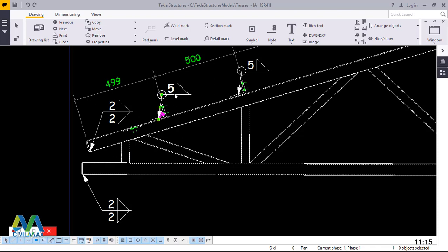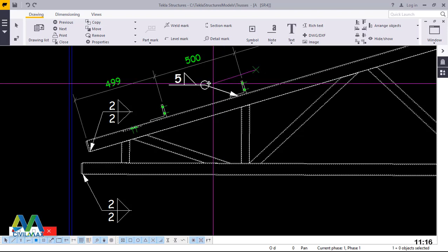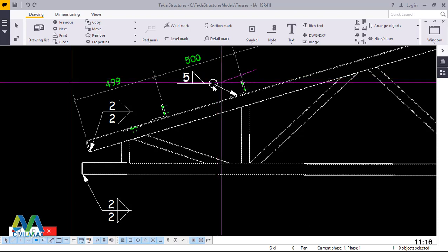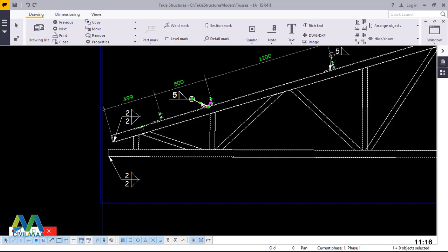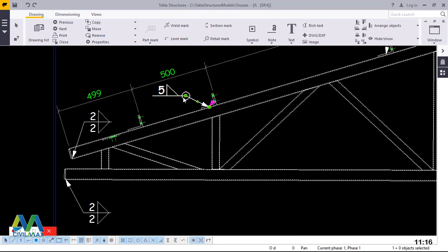And this is 5 millimeter thick, which is not necessary, but this is just a default setting, and we can get rid of that. Just delete that. And also this, you can see the circle inside here means weld round, but one side. This side we weld round with the thickness of 5 millimeter thick of weld. But 5 millimeter thick is too big for this, but the 5 is just a default setting from the system, and this can be customized to make it 2.